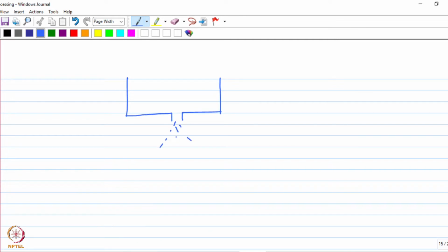So therefore, into this stream of the molten metal, the reinforcement particles are added at a location when these metal droplets are still in the liquid condition, right? So therefore, a variation of this could be to have these particles added at a location of the stream where it will be in the two-phase condition.